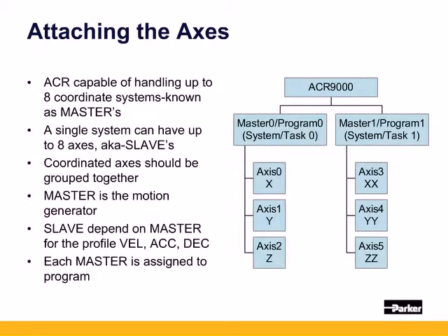name. Also note that programs 8 through 15 share a 1 millisecond time slice and are non-motion programs. These non-motion programs allow you to run tasks continuously in the background, handling communications, monitoring inputs, and setting outputs, etc. Use INH inhibit command carefully in progs 8 through 15. If you inhibit one, all are inhibited until that bit evaluates true. In the motion programs prog 0 through prog 7, the INH inhibit command in one program does not affect the other programs, as they all have their own time slice.